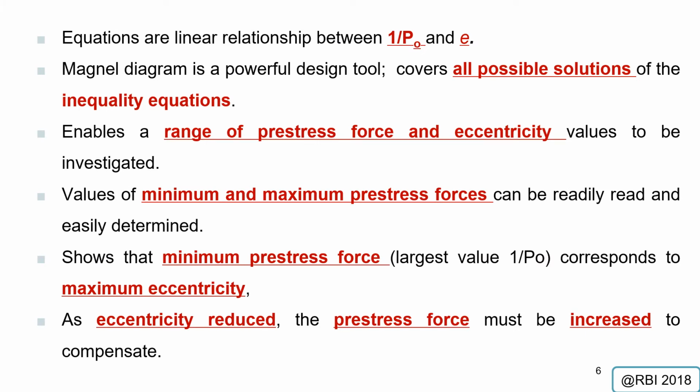One thing you have to take note of: all the equations that we form here, the four inequality equations, have a linear relationship, meaning you are going to get a straight line for each equation. So the Magnel diagram is a very powerful design tool which covers all possible solutions for all the inequality equations that we have. It enables a range of pre-stress force values to be investigated. You will get the range of pre-stress force and eccentricity.